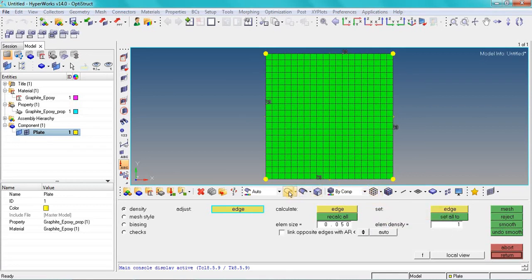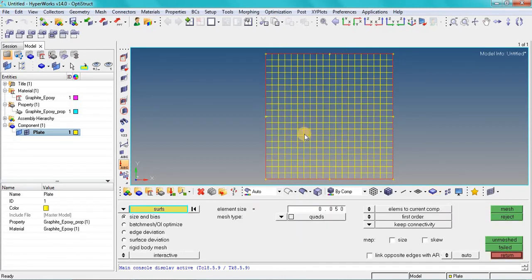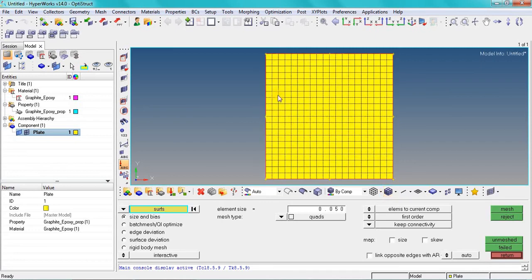Okay, now click on this button, which is wireframe geometry. Okay, sorry, first I have to press return. Once you press return, okay, that option is visible here. So by clicking this option, yes, it becomes wireframe. Now you can click this option to see only the elements. So if you click this option, it also shows the component as well, the surface as well.